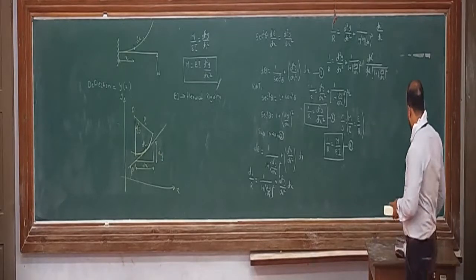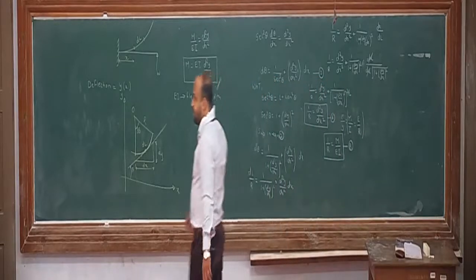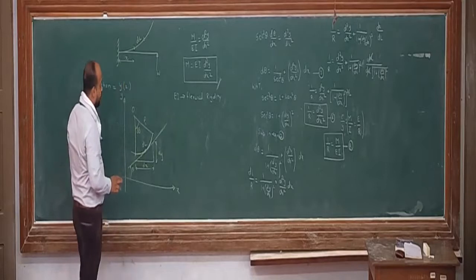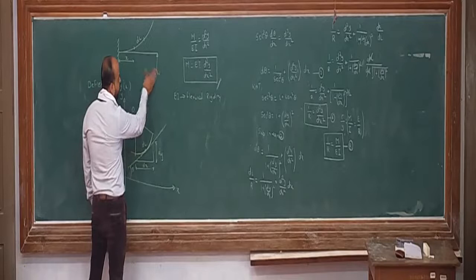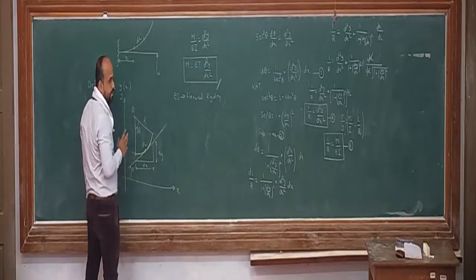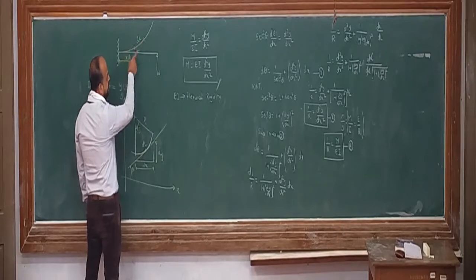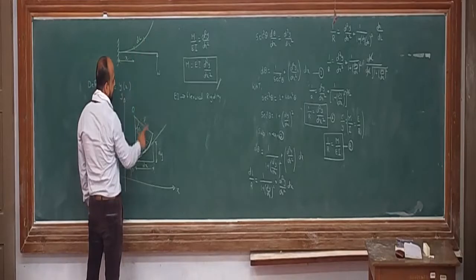Okay. So quickly I will tell what all things we have done. First, you have to take one cantilever beam which will be subjected to the point load as shown. Initially the condition of beam is like this. When we apply load, beam will deflect into some curve. On that deflected curve, I will take one small random portion at a distance of x from the fixed end. Now this is enlarged here.